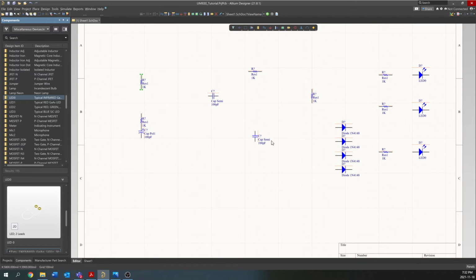Lucas has a question here. Can we change footprints after making the schematic? Absolutely you can. I will demonstrate that for sure. That is definitely something you can do. The schematic symbol is not locked to the footprint. You can go back and forth and change it after, and that happens all the time. You might forget to do that, start laying out your board, and then go, oh no, I have to change it, and then go back and change it, or select a whole different component overall.